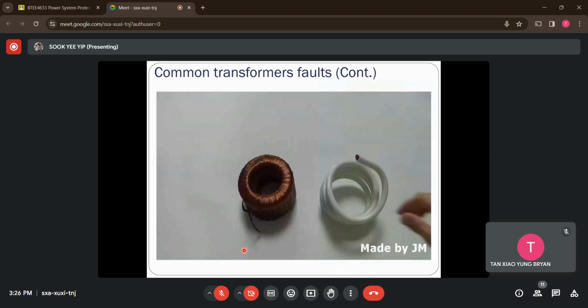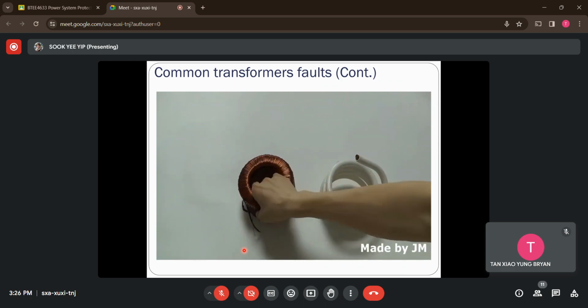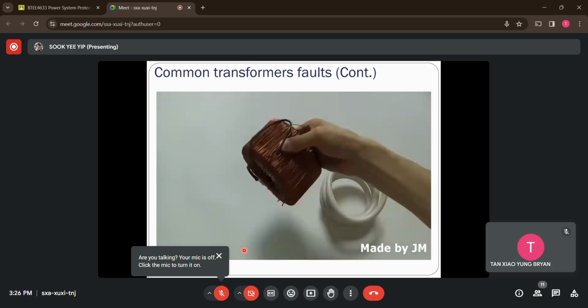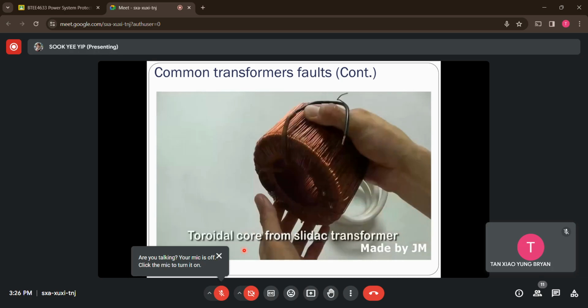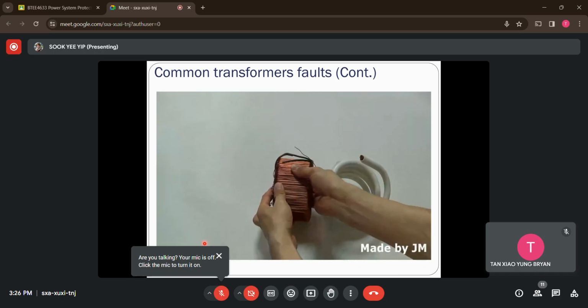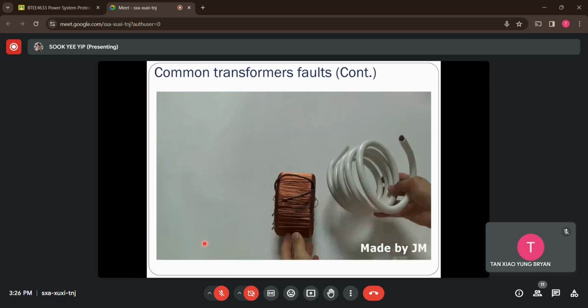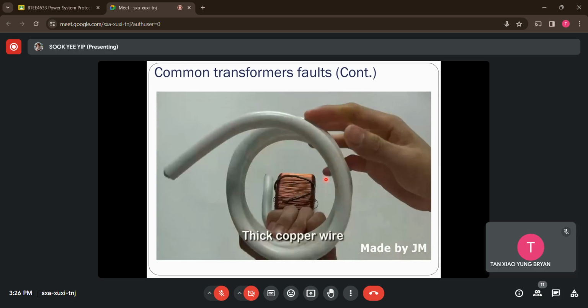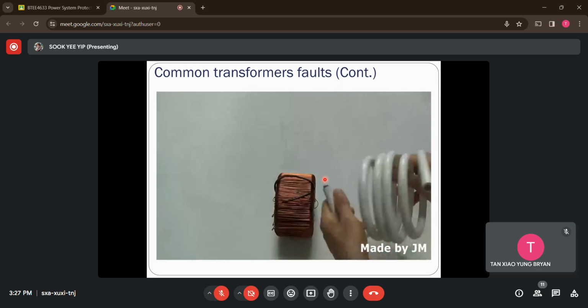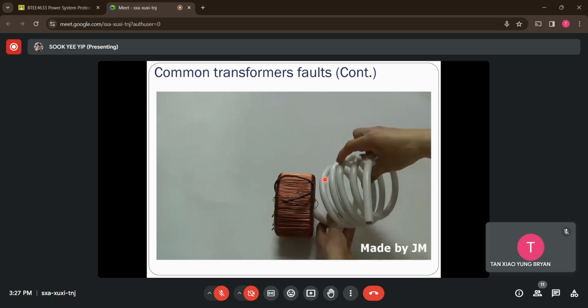All right. So I have one video here without sound, where there's a guy trying to simulate the inter-turn fault for the transformer winding that is being operated with 1000 ampere. I will put on this video here. So he's trying to construct a transformer using a toroidal core. Here is the kind of material for the core. Judging by the size of this wire here, the thicker one, we are expecting it will have high current flow. The thinner one will be for lower current.